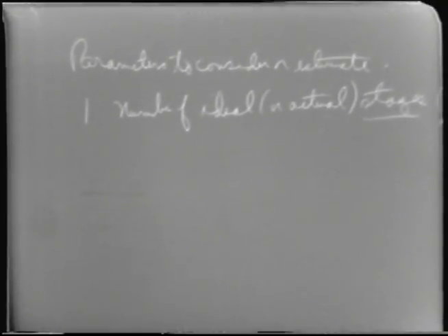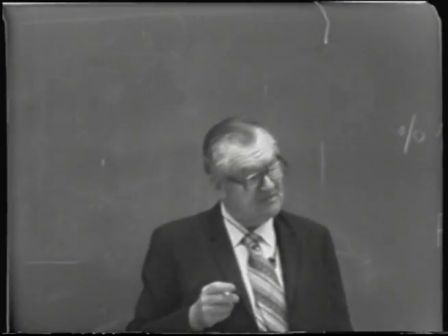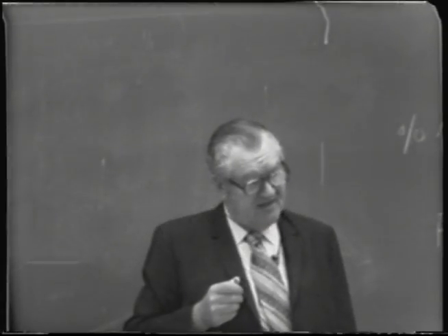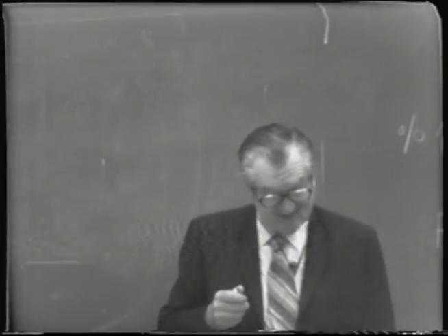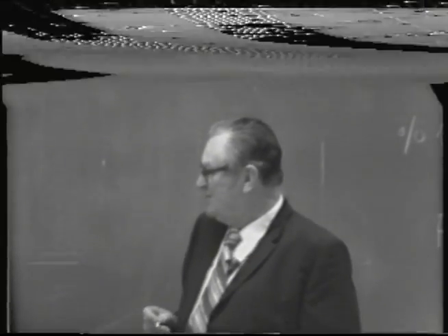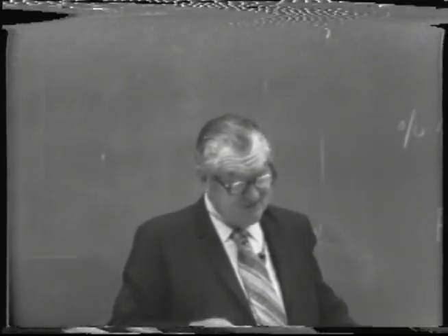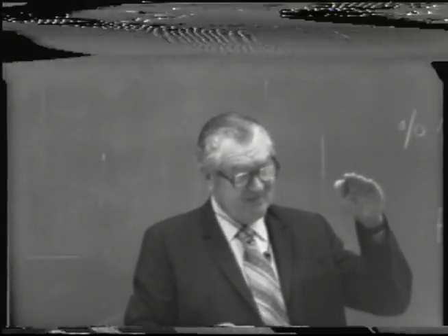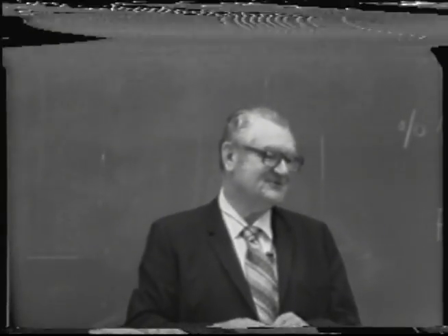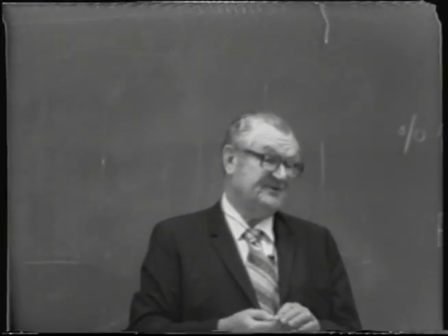In actual design, how would you state that if you're using a packed column? Well, in terms of packed columns, that's another thing I was coming to. We still calculate the number of ideal stages, and the usual treatment is to estimate the height equivalent to a theoretical plate of a packing.